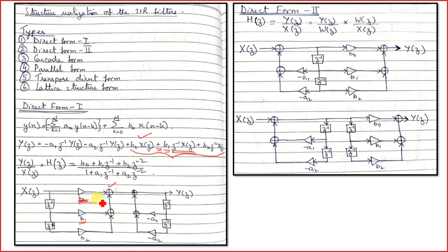Okay, then similarly, as we go forward, we have input which has been delayed by 2 units. We have already delayed the input by 1 unit over here. Then in the next step, if we again put the delay, we will be getting the input post this delay as 2 units of delay, and that delayed input is getting multiplied with b2. So over here, see, it is getting multiplied with b2, and then it is getting added up with the previous two input components, right?